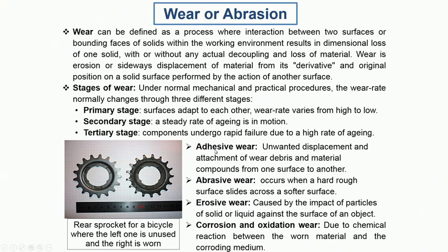So in case of adhesive wear, what I was saying just a few minutes ago, we anticipate that there will be some amount of temporary bonding between the surfaces, or forces of adhesion, followed by dislodging of those bonds, and in the process we lose some material from either of the surfaces. In abrasive wear, we encounter a situation where a harder surface or harder particles are sliding against a softer surface, leading to certain loss of material.